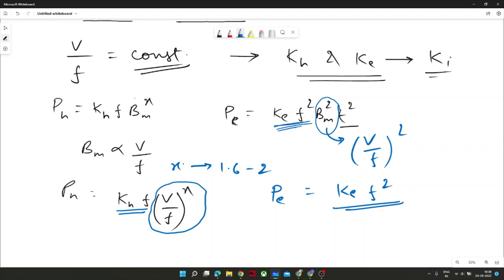Why does frequency matter in a transformer? Because if you go for high frequency, your transformer will become smaller and smaller. The same thing happens with a motor or generator set. If you go for a high speed motor, your number of poles would get lower and your motor size would become smaller and smaller. But at the same time, your eddy loss and hysteresis loss would also get added up. It would be significant. You see, it is varying with f square, so that is quite huge.